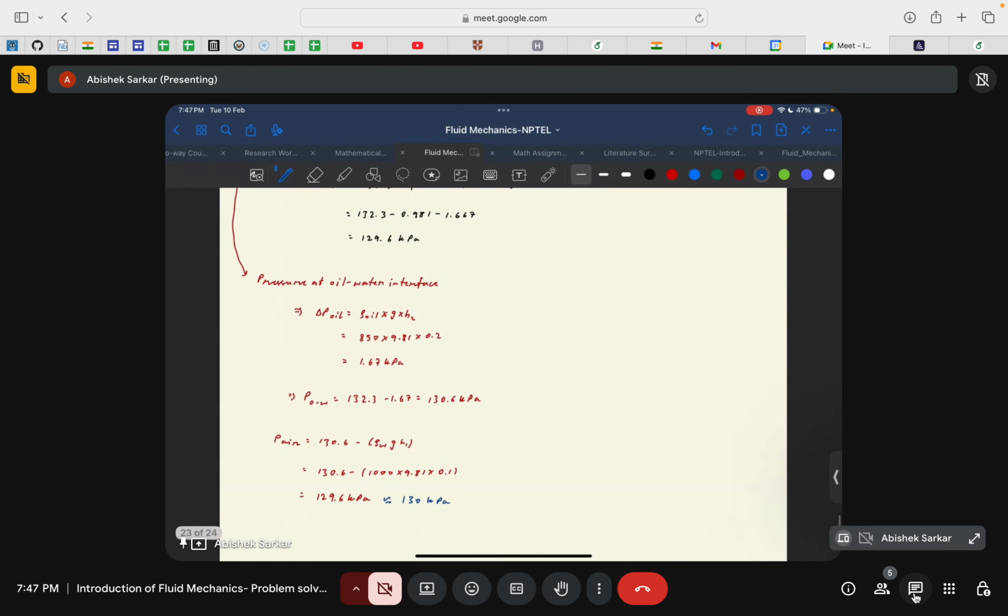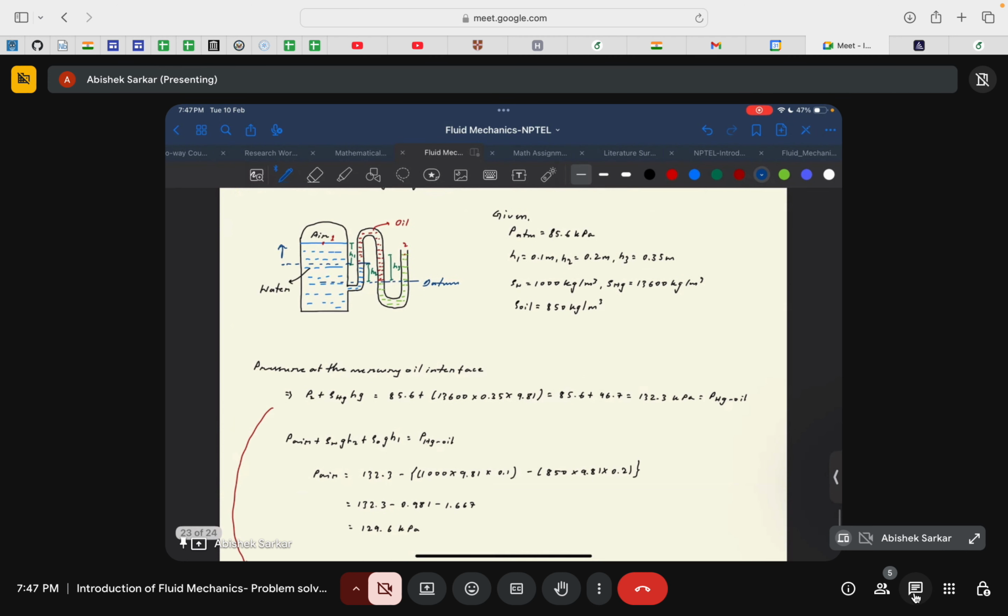Okay, so it is actually a better practice that you change your reference point from one point to another, because there are multiple fluids, so you need to choose the datum in a way that the fluid at the interface is the same. That's why we cannot go from this particular case, because the fluid at this and this interface are not the same. I don't know how I did it actually. I will look into it once, then maybe I'll clarify later, but I think this way is much better for this kind of problems.